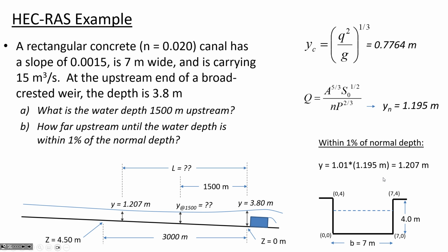And so what that looks like is, for our channel that's just upstream of the weir, these are the coordinates of the edges of the rectangular channel. So the reach station is starting at 0 here and working upstream, and then the cross-section station is starting at this location and working sideways. The station is what distance horizontally we are from that left edge. And we're not going to worry about the geometry beyond the banks. In a real-world application, you'd want to know what the geometry of the floodplain looks like. We're just going to concern ourselves with this main channel for that example.